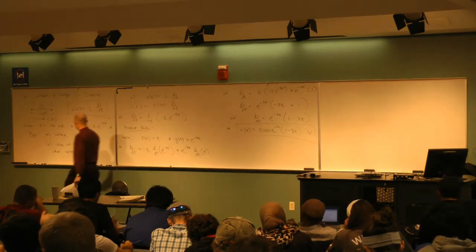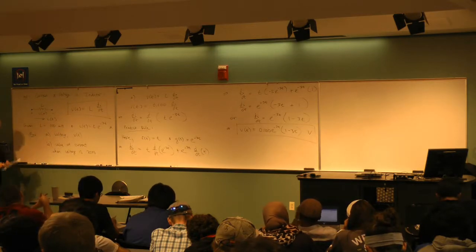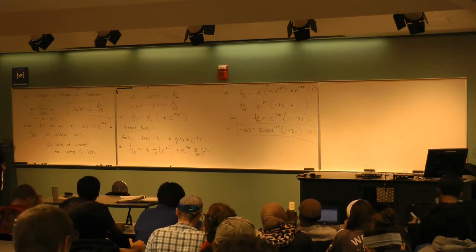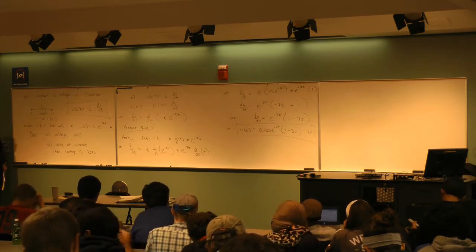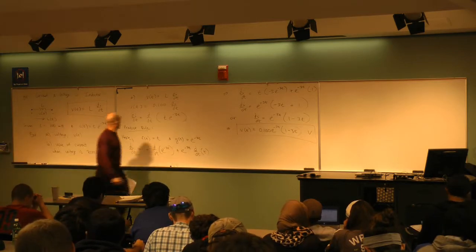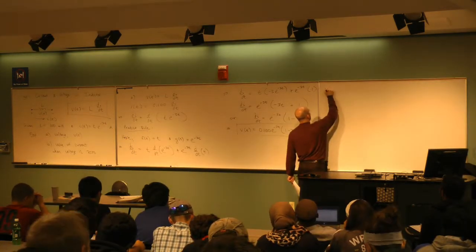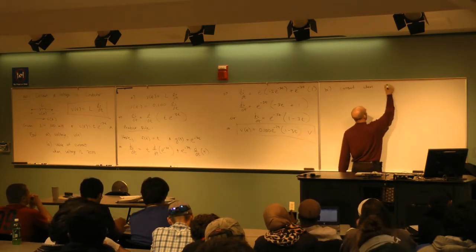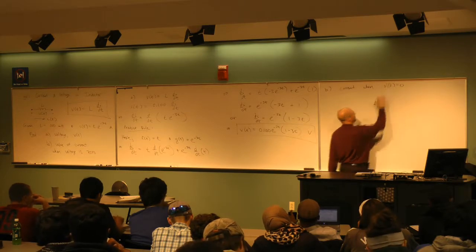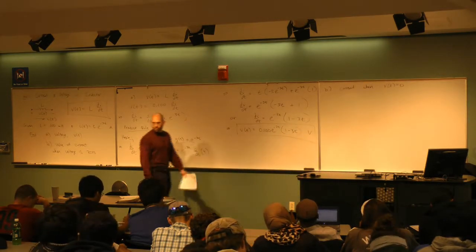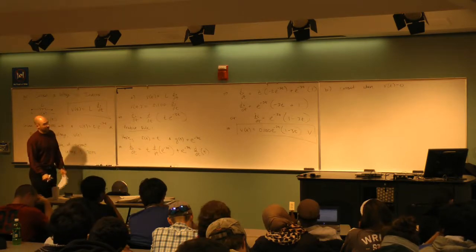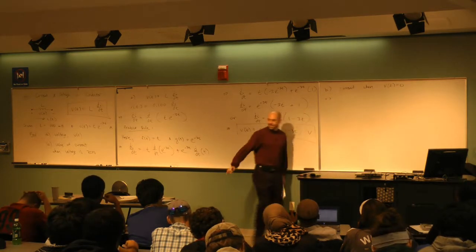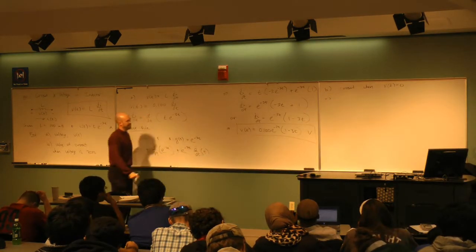All right, so we have the voltage. The question now is, what's the value of the current when the voltage is equal to 0? And we want to know that. Why? Current when V of t is equal to 0. If I find that place, that means the slope of the current is 0, which means the current is probably a what? Maybe a max, could be a min. It's a flat spot.